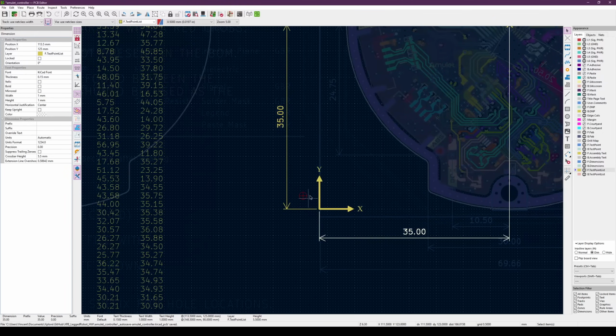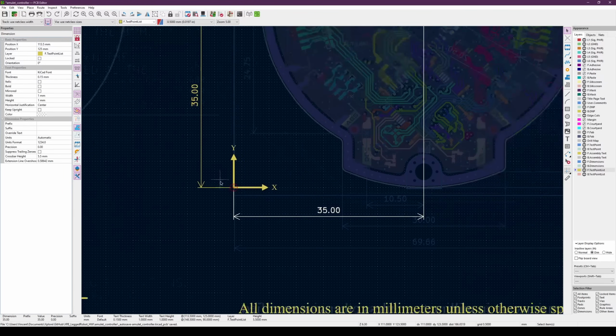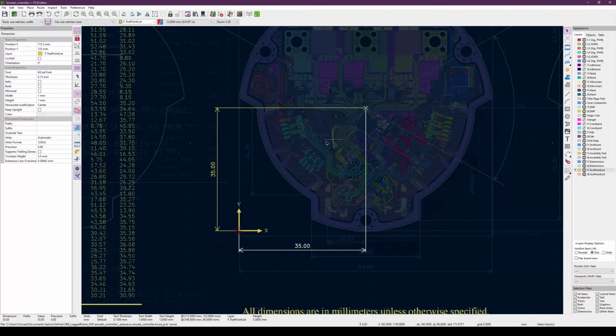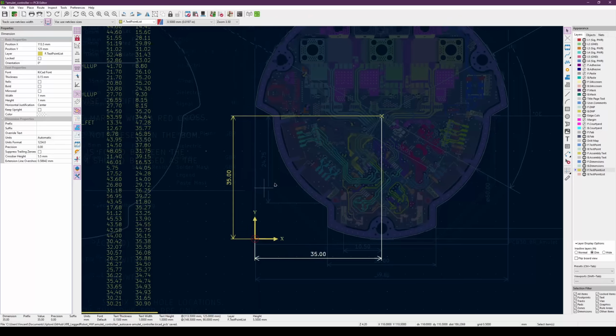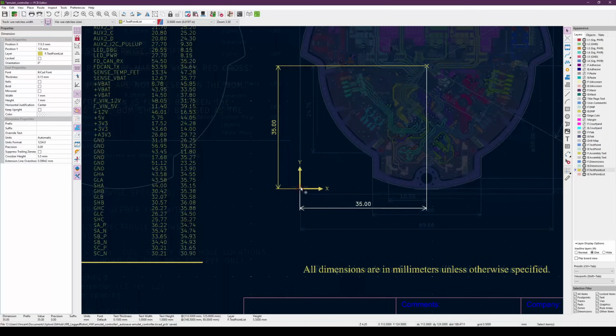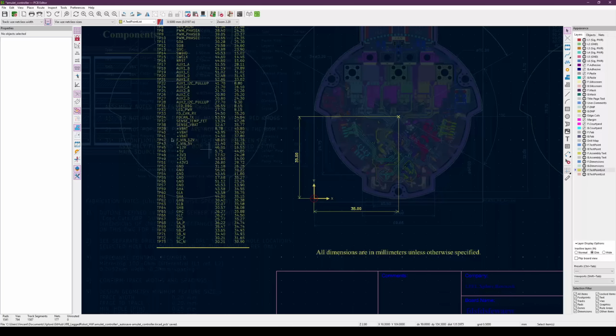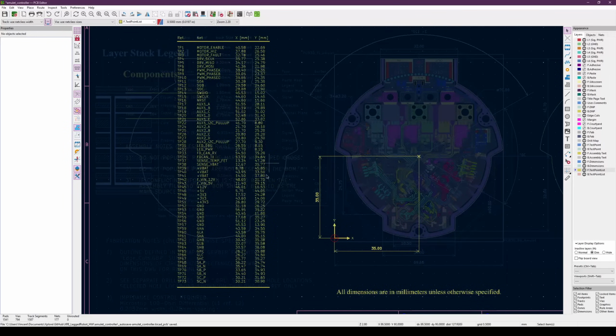So you can simply change it here, and this will give you the 0 point of each part of your PCB, like the components as well as the test points and so on. So I just add this here and also add these indications so that the mechanical engineer can maybe design some sort of bed of nails, for example, if he wants to do automated testing using these coordinates.